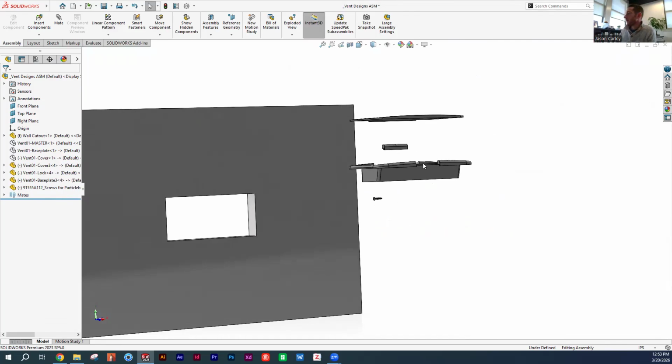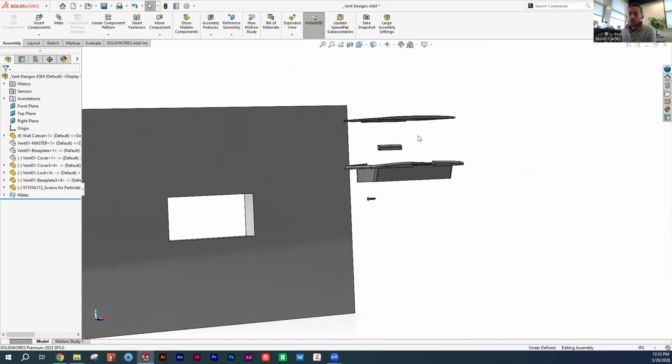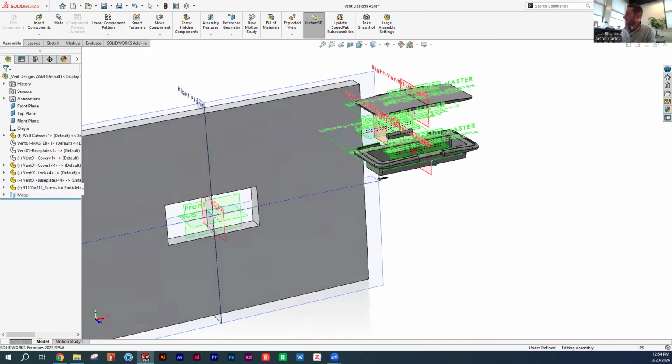So mating is how you basically locate a part in your CAD file and make it dynamic. So you can select edges, faces, vertices, axes, whatever is most appropriate for your object. So I'll show you how I place these, and I'll do them one at a time.